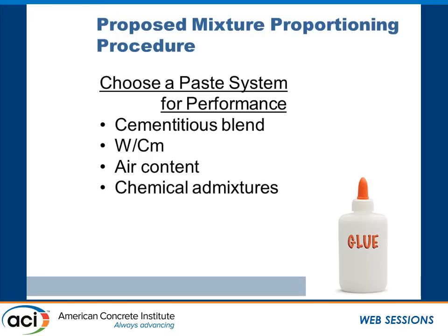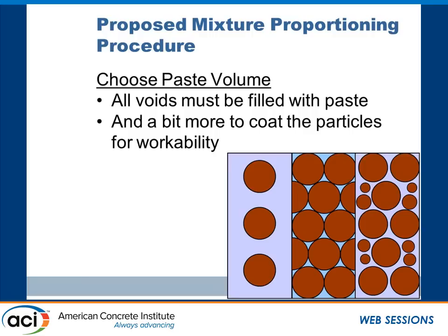And there's the rub. Charles Nye is not in here, so I can say admixtures seem to be less stable. And I'm seeing it often. You get 6% in front of the paver and you get 3% behind the paver. Is it going to be durable? No. The other one is we get 6% in front of the paver and 16 behind the paver. And then your strength goes south. So we have to watch out for the stability of our materials and calibrate for them for the equipment that we are using. All right.